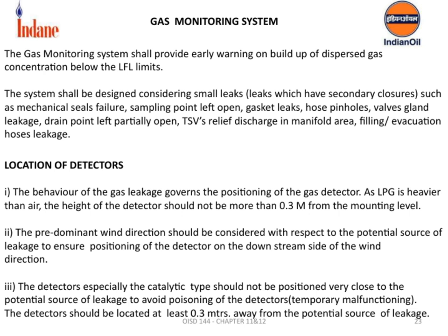In essence, the system should be sensitive enough to detect the buildup of gas concentrations below the lower flammability limit, giving us enough time to respond before a dangerous situation develops. By considering all these factors, gas behavior, wind direction, detector placement, and system sensitivity, we can ensure a safer environment and effective leak detection.